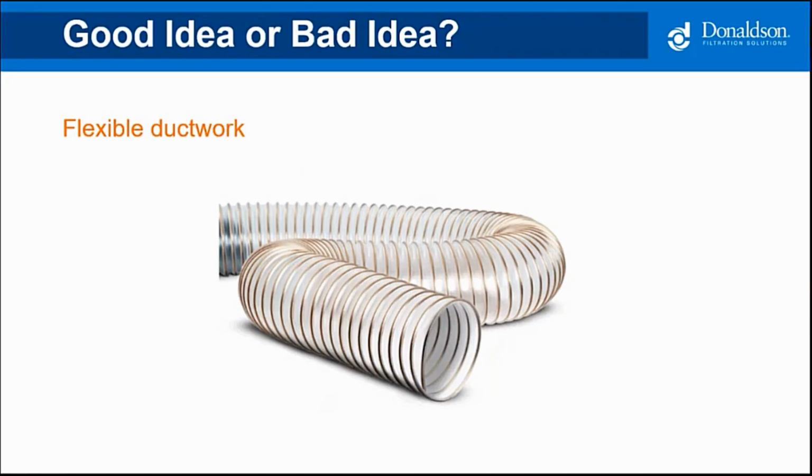you have a piece of flexible duct. Flexible duct has about 2 to 3 times the static loss that a galvanized piece of duct would be. So if you said thumbs down for that reason, you are correct.